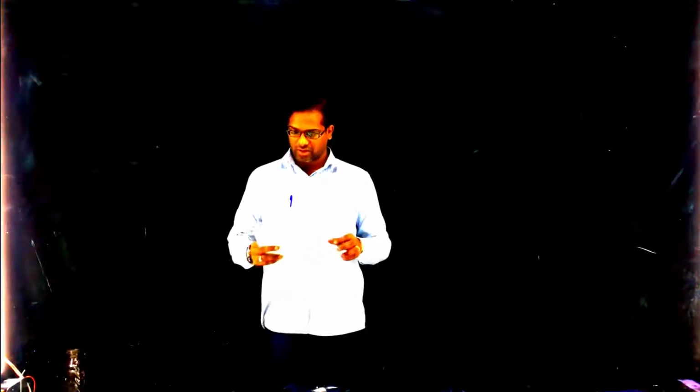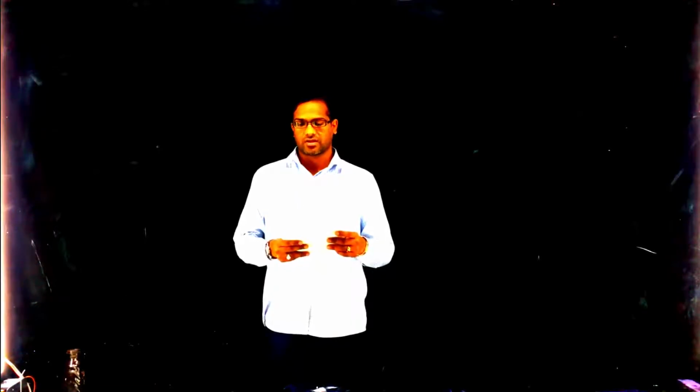So here we have a small problem which I would like to dictate for you and solve for you. A reinforced concrete beam has the following data. Width of section 300 mm. Depth of section 500 mm. Here it is said that it is a depth of section. It didn't mention overall depth or effective depth, so because it is not given, you can consider it as your overall depth. Depth of section 500 mm.